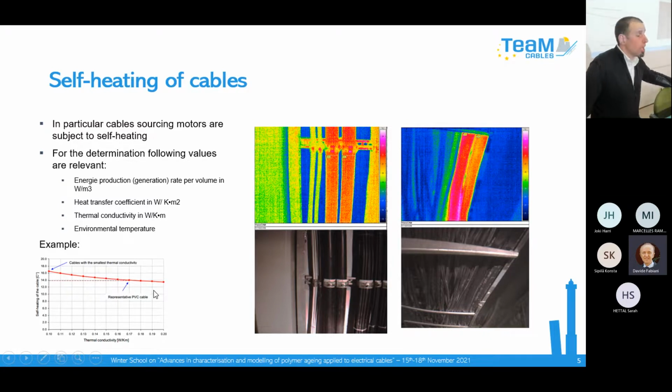the core temperature, and this temperature is important when, as Karel also showed yesterday, you calculate the residual lifetime of the cable. You do it in connection with the environmental temperature, and you have to add the self-heating on top. And this is the representative temperature you use for, for example, your Arrhenius model. Mostly we work with the Arrhenius model to calculate the residual lifetime.